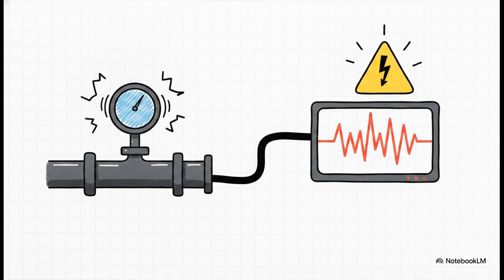A vibrating compressor skid will slowly but surely destroy the accuracy of that transmitter. All that vibration mechanically agitates those delicate capacitor plates, or the resonant wire if you used one of those. What happens is the controller receiving the signal ends up frantically chasing noise instead of actual process changes. Without isolation, your accuracy is totally degraded, and honestly, nobody usually notices until the safety system is right on the edge of tripping from a false reading.